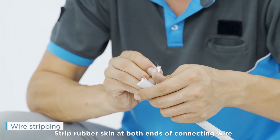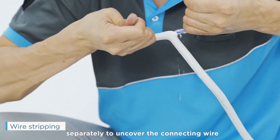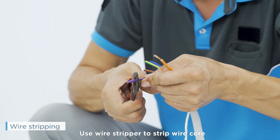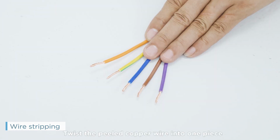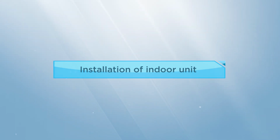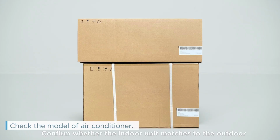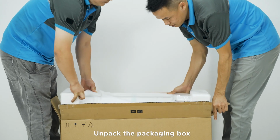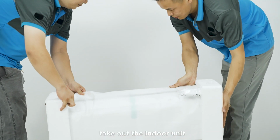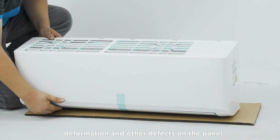Strip rubber skin at both ends of connecting wire separately to uncover the connecting wire. Use wire stripper to strip wire core. Twist the peeled copper wire into one piece. Installation of indoor unit. Confirm whether the indoor unit matches the outdoor unit according to the model of purchased product. Unpack the packaging box, take out the indoor unit, and examine whether there is any scratch, deformation, and other